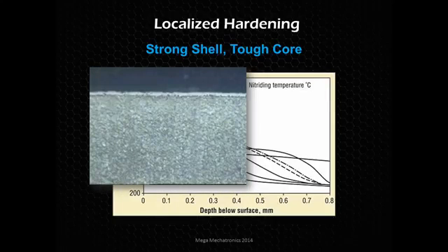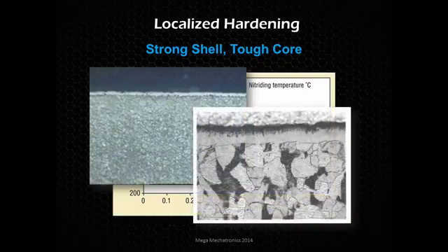And here's a close-up view. So you see that white layer is a different crystal structure, so it looks a little different, and as we're getting up a little closer, you see those grains, the light grains and then that dark, and those are different alloying elements and things like that. And then you can see that nitrided layer with again a different structure, and smaller grains, you can't see the grains.